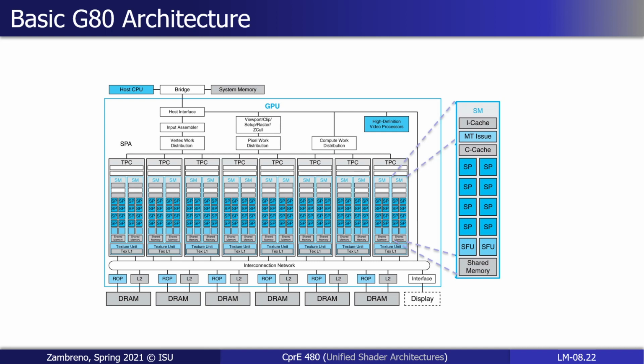So we can have an adder in our vector shader implementation in our lab GPU, but we probably don't want to put four of them in there. That's just a trade-off we're making. If we were to put four of them in there, we could get slightly more parallelism out of our division operation. Well, division is not as common as addition, and not as common as multiplication, and not as common as load and store. And secondly, by doing so, we could fit maybe fewer of these in total in our total chip budget.